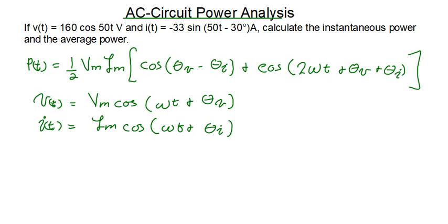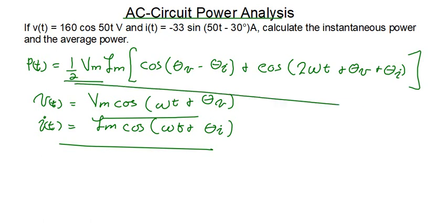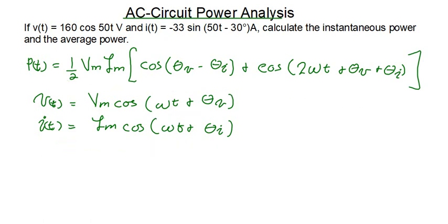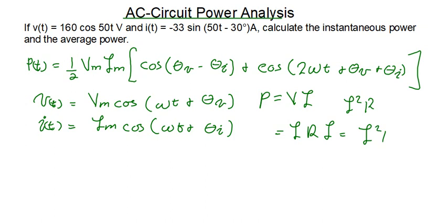Okay, so now how do we move from this to that? Because from what we have here we come to this. We know that power is simply calculated by voltage by current. You might also find that power is determined by current squared by R. How does this come about? It's very simple. We know that voltage is current by resistance, and we still have this current here, and we multiply by that current. Hence you're going to have current squared by R.